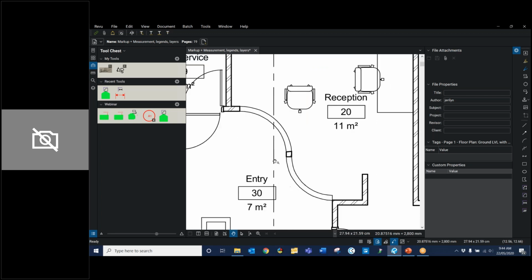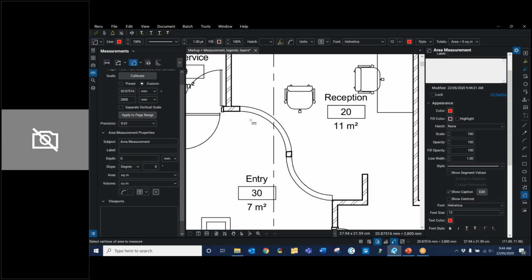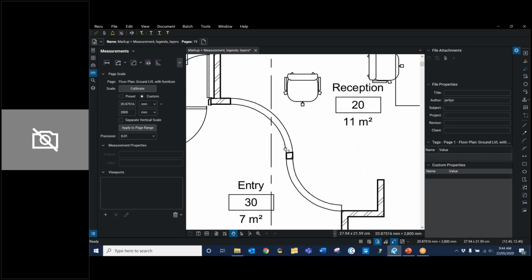We've got a curved surface here. Most people, when they first start using Bluebeam, we went through this last week briefly, usually just get the area tool and click on points close to each other so they get really close as they go along the curve. It takes quite a while, it's a cumbersome process, and it's not very accurate either. You can see some of the lines aren't quite accurate, and that's just gone crazy anyway.